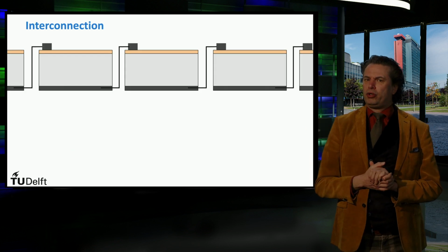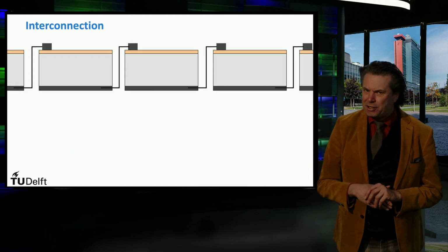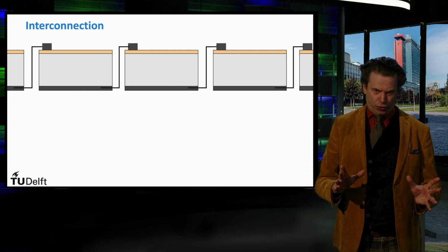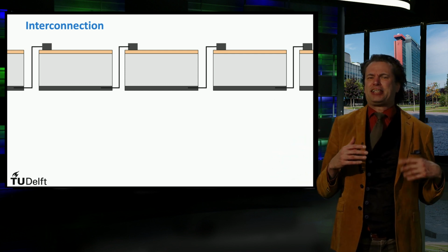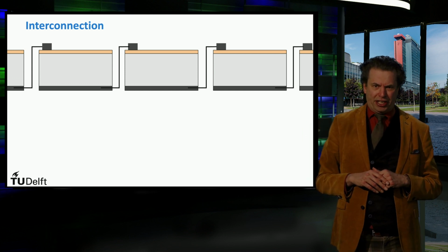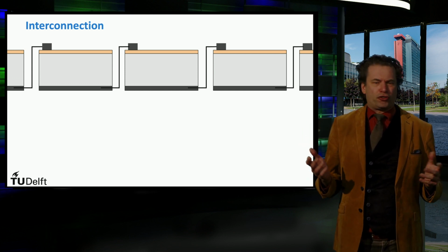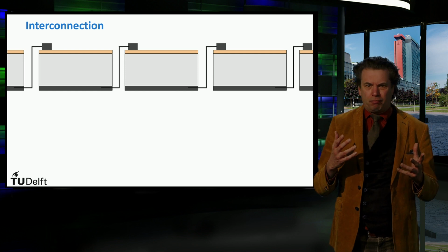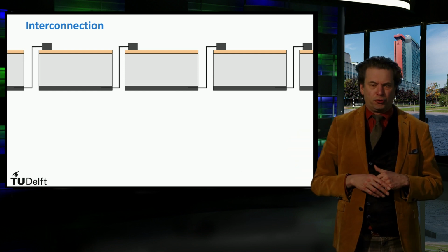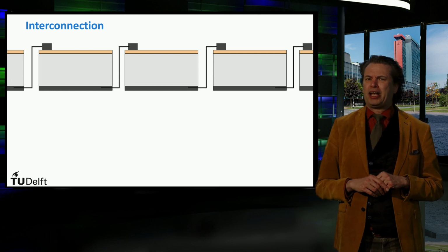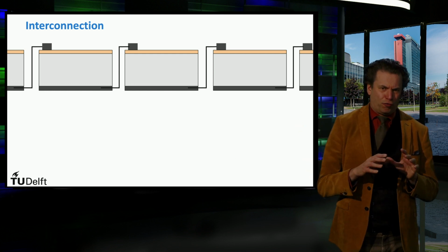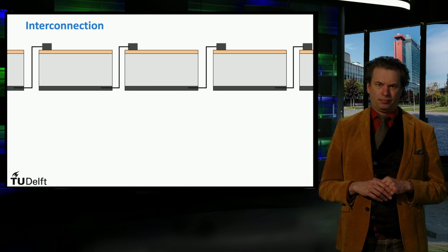A solar module consists of many solar cells interconnected in a circuit. As of today, the most frequently used design has 60 to 72 individual cells with total dimensions of 1 meter by 1 meter 65 up to 2 meters. In photovoltaic systems, these modules will again be interconnected to form an array.